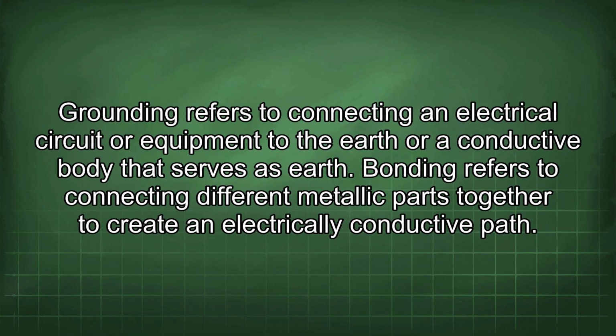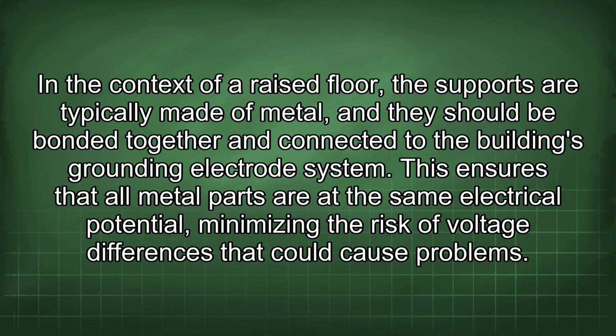Grounding refers to connecting an electrical circuit or equipment to the earth or a conductive body that serves as earth. Bonding refers to connecting different metallic parts together to create an electrically conductive path. In the context of a raised floor, the supports are typically made of metal, and they should be bonded together and connected to the building's grounding electrode system.